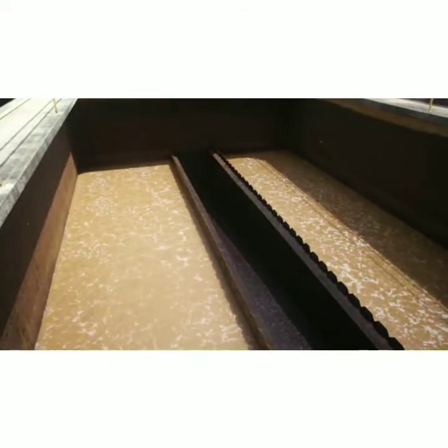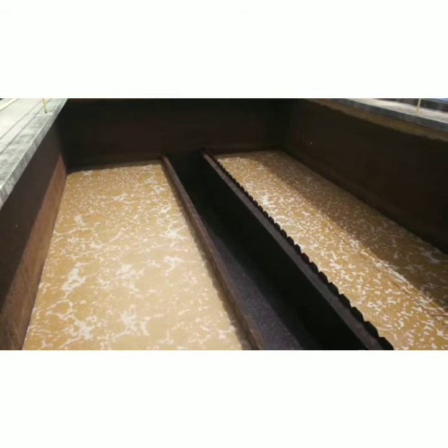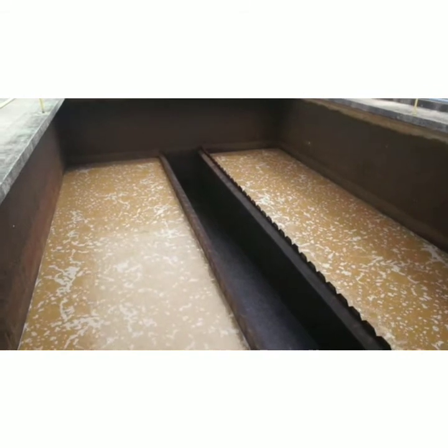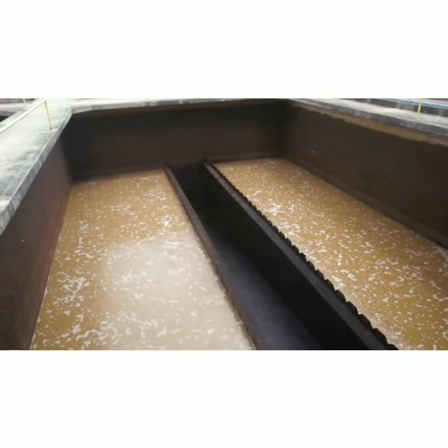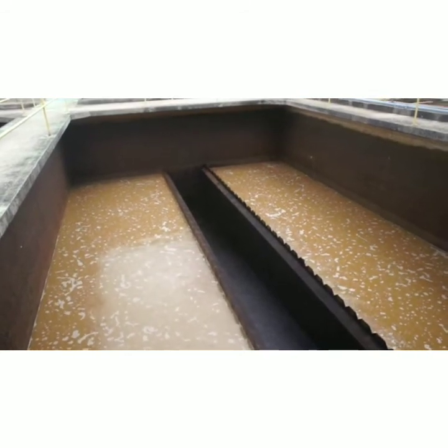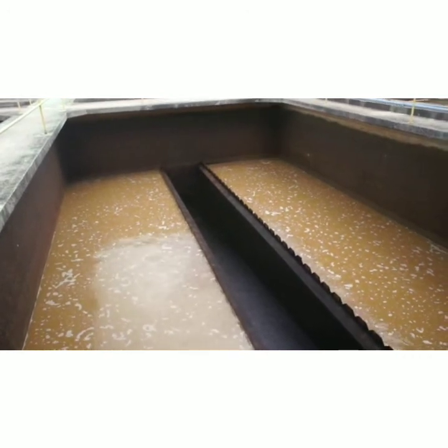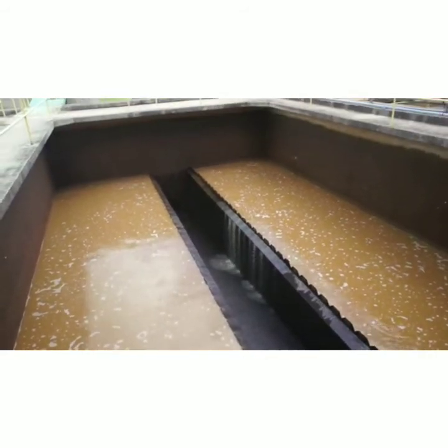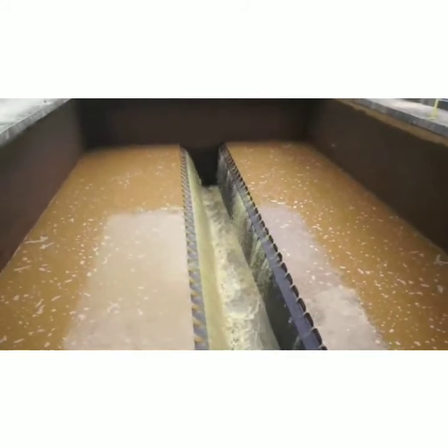Just see it once. Very slowly they are raising the water level. They are supplying the backwash water from the downside, so it should not get disturbed much. Just see, it comes to the top and flows, carrying the impurities, and it goes to the middle row. Can you see, it is falling into the middle row, that is actually the water troughs.